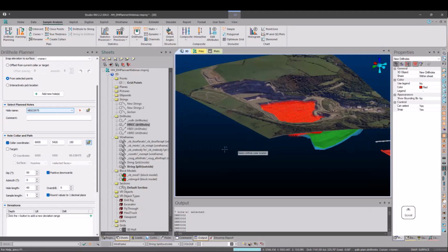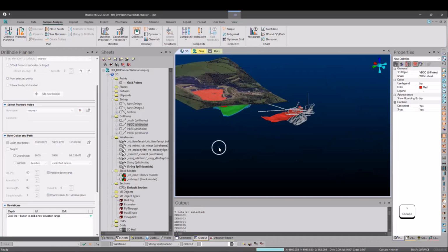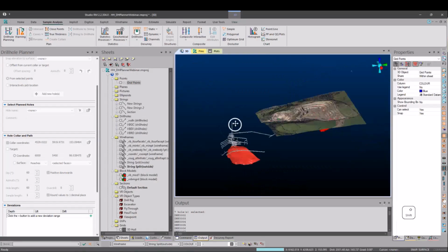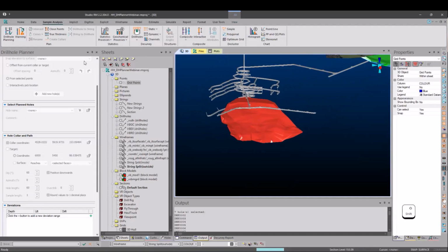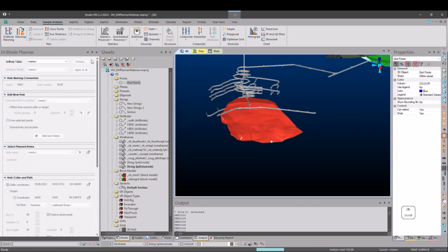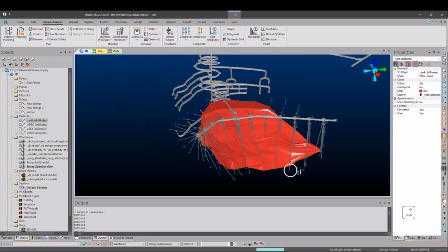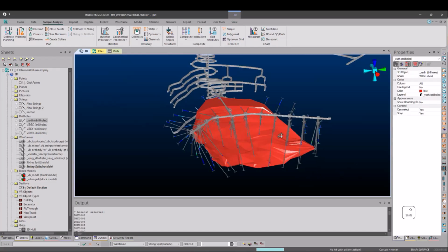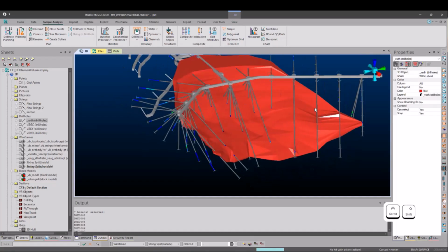And finally, for my underground friends, more often than not, whoops, don't need the points anymore. So the idea is the same. You want to generate a bunch of regularly spaced points along your mineralization, or more or less your pierce points. More often than not, you already have some. By the time you get to the underground stage, you already have some of the drilling. So maybe you want to infill it. These are 50 by 50 meter drill spacing. So maybe I want to infill it to say 25 by 25.